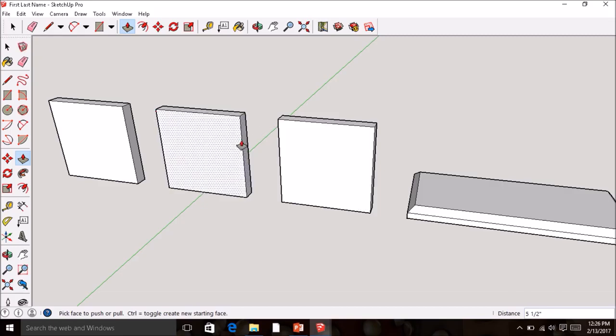Another one is going to be angled, and another one is going to be round. So we're going to start with the angled one over here. To do that, I'm going to select the line command, and I'm going to draw over from the endpoint along the edge 1 space 3/8, and I'm going to hit enter. You'll notice I now have an endpoint right there. I'm going to do the same thing along this line.